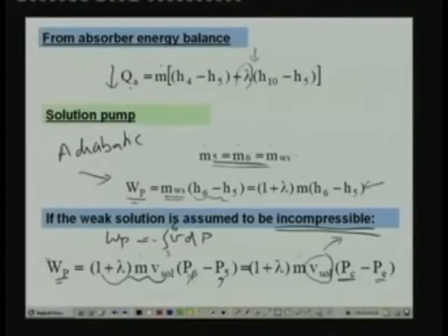The power input to the solution pump, if you remember, is negligible compared to the heat input to the system. That means in COP calculation you can neglect the solution pump work, but you still have to calculate the amount of work required by the pump, because when designing the system you have to select a suitable pump and motor. That means you have to specify the required capacity of the motor, so for that purpose you have to know the work input to the pump.